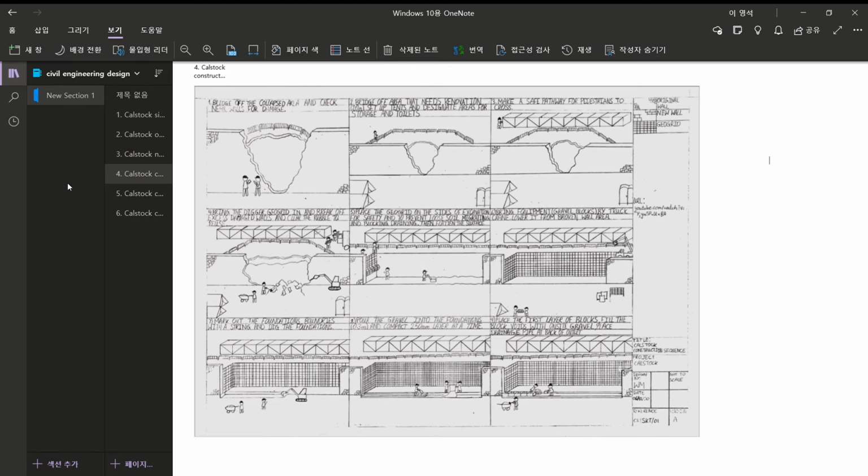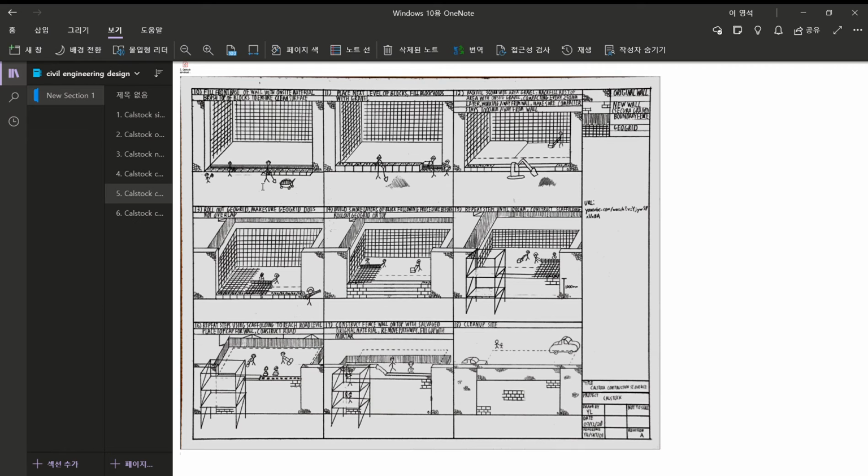The drainage pipe will be placed behind the first layer of blocks. The pipe is placed there because the gravel is permeable. All the water will go down to the drainage pipe and it won't collect behind the wall. Next, we will fill the front base of the wall with on-site material and brush the top of the blocks to ensure the next layer is level, after which we will be placing another layer of bricks and filling the void